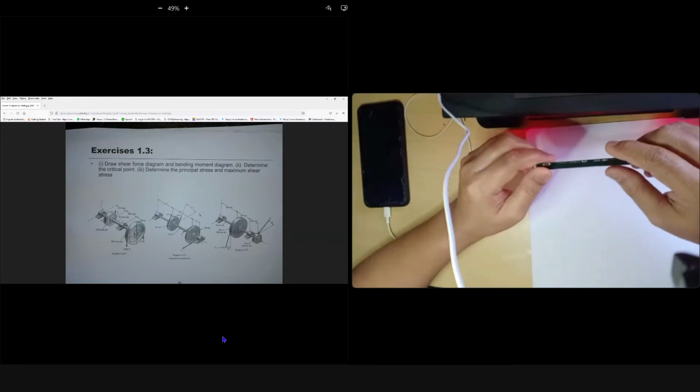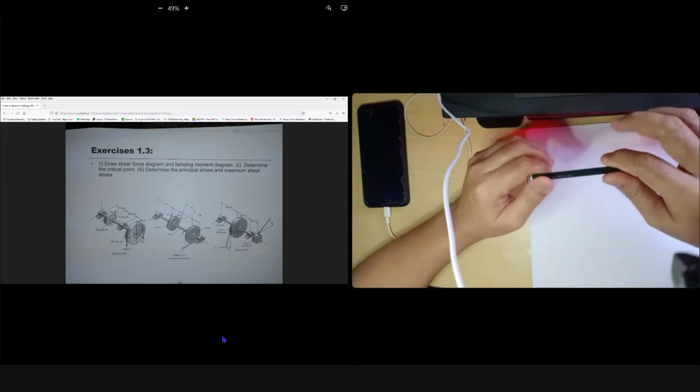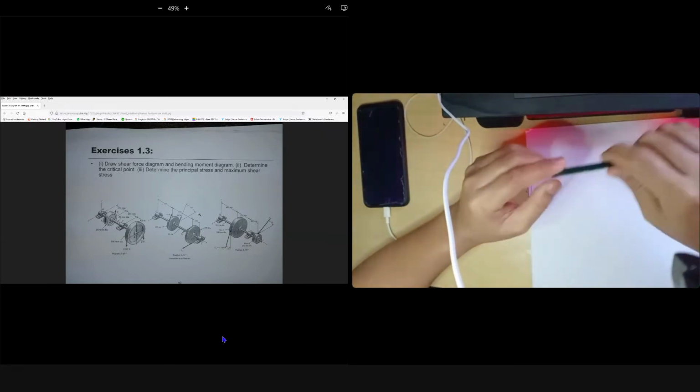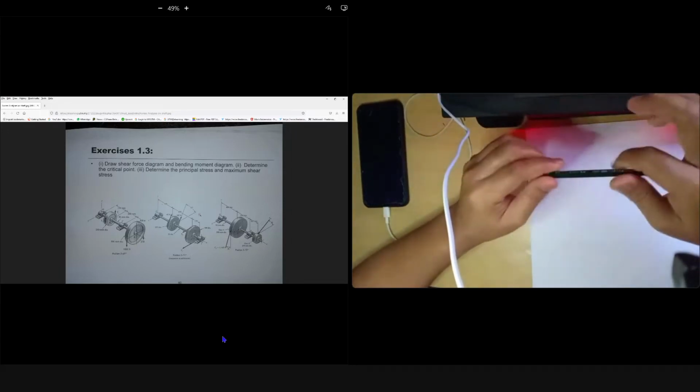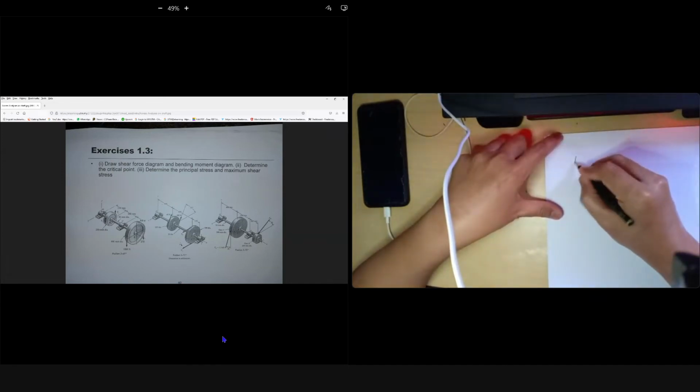Normally with a shaft, you solve the shear diagram and moment diagram. On the shaft we have shoulders, maybe we have grooves, maybe several notches. Always read the question, do not panic. Sometimes the question is actually simple and easy. Sometimes it asks which shoulder is critical. Look along the shaft to see which one is critical. Much of this is in the e-learning. That's why the first thing we should do is the FBD, right?